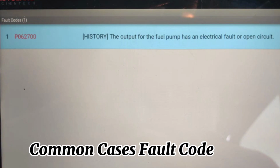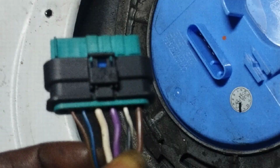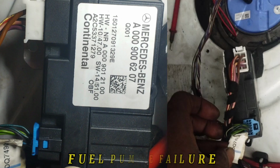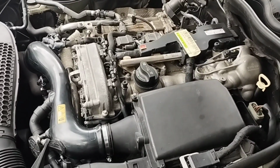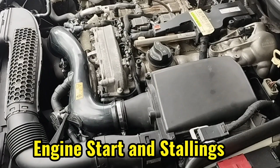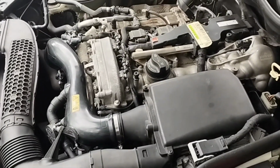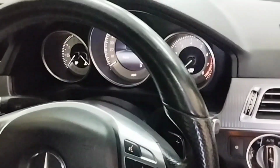Common causes of this error code include fuel pump problems, wiring problems, a bad CAN bus, circuit problems, and PCM failure. A vehicle logging this code can have reduced engine performance, hard starting, engine stalling, or misfire. With the ignition switch off, find where the fuel pump is, to check the fuel pump and wiring.